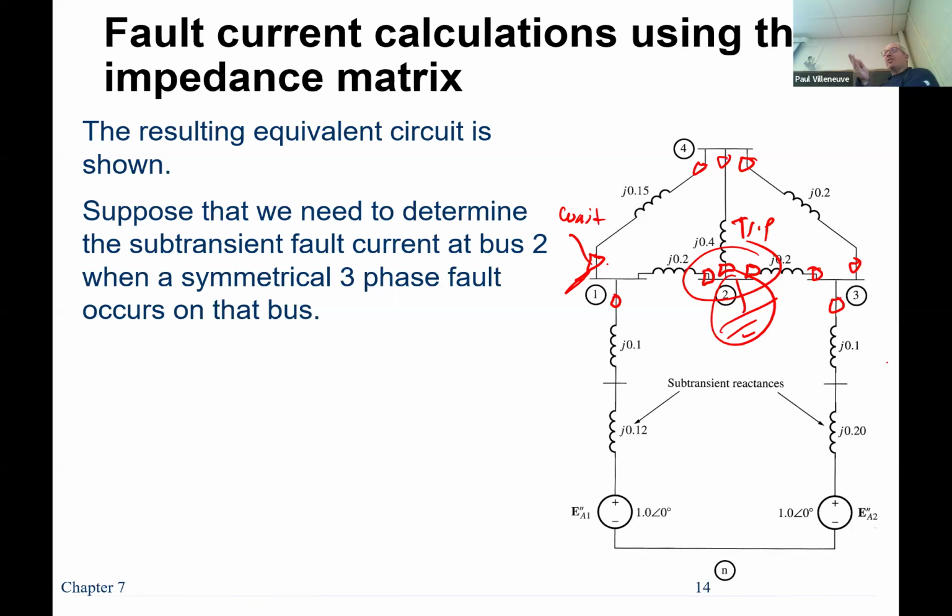We talked about it a little bit, but the system is less reliable, right? Because now I have kind of one line that's only energized at one side. So there's no power flow that can go through there. So that's useful. What else? What's the most important part? Well, maybe not the most important. It won't be damaged if you take those three closest breakers out of service. If everything trips pretty fast, you should be protecting your system from damage. Anybody want to guess as to what the other one, which is probably in some ways more important?